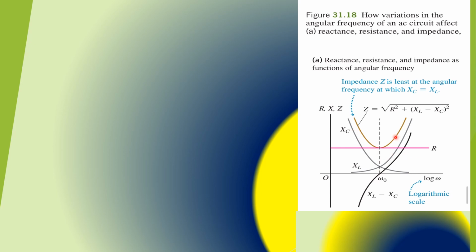And you will notice that the impedance has the least value at a certain angular frequency where the two reactances, X sub C and X sub L, are numerically equal.